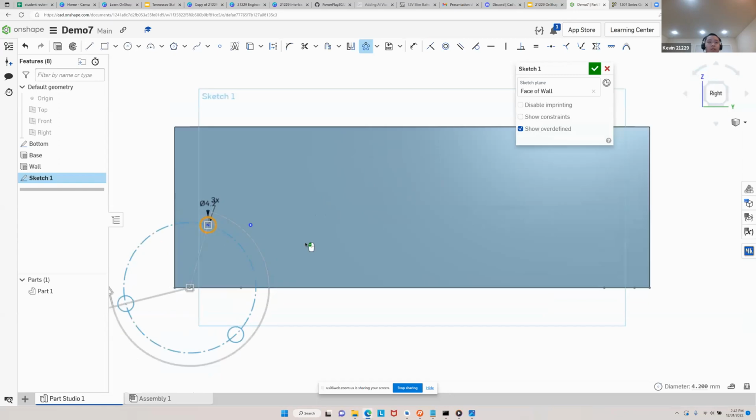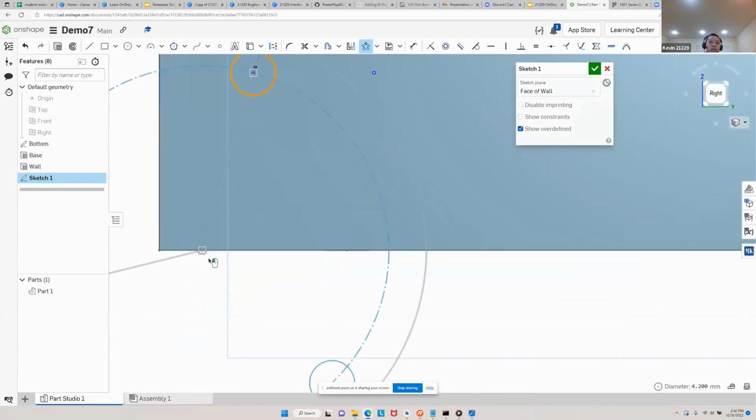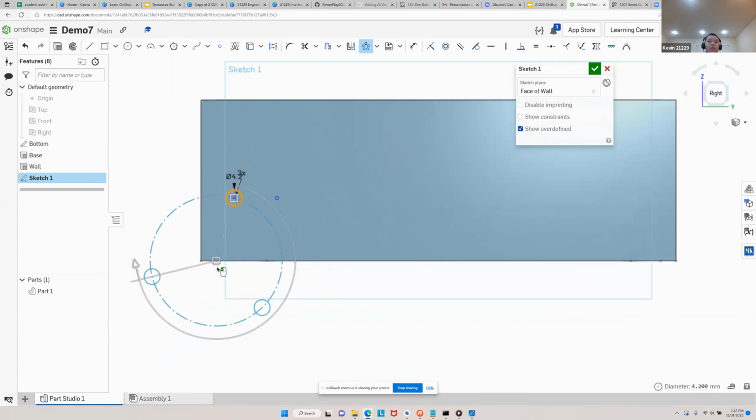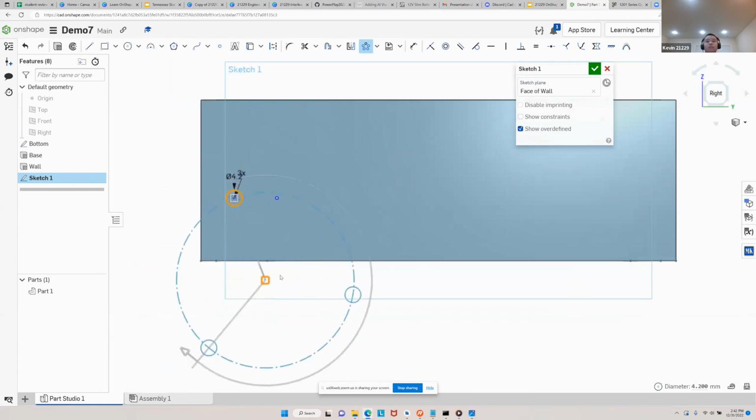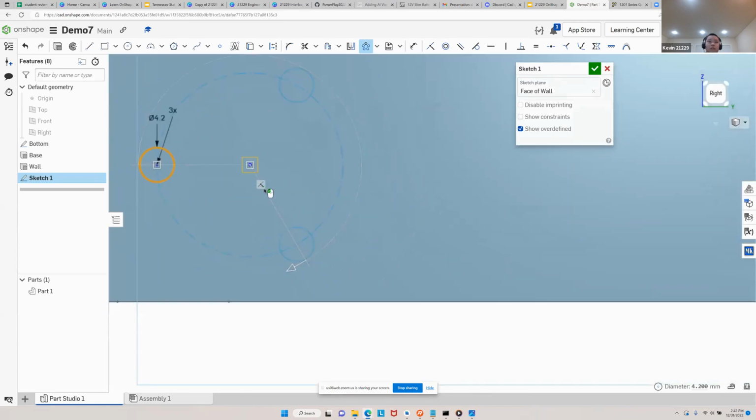You should probably scroll out, and then you'll see that these circles seem to be revolving around a point, which is boxed in gray. We can drag this point around. So this point will be coincident with the point we just created. You'll know this happens when we see this coincident constraint icon. It has like 2 lines intersecting at a point.